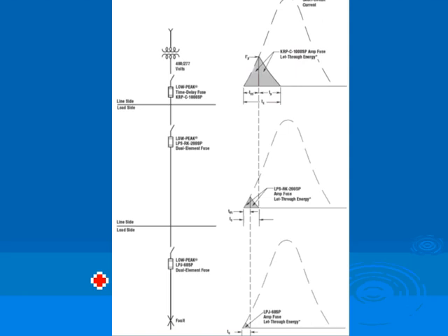But if you care about what category that guy or gal who are working right here is going to wear, then you get into low peak current limit fuses. Low peak current limit fuses. These guys not only trip to protect you from overload and short circuit and ground fault. That's must by code. But also, they trip fast enough that will limit the amount of heat that will be generated because of a short circuit and magnetic force that will be generated because of a short circuit. When you have a short circuit condition, guys, you have two forces working on that. One force is called shaking and baking. I call it shaking and baking.